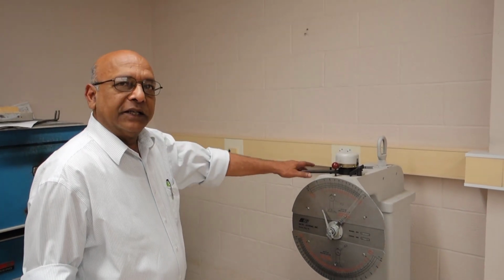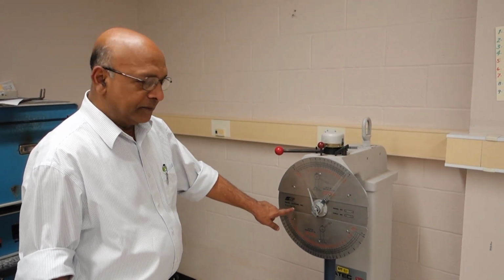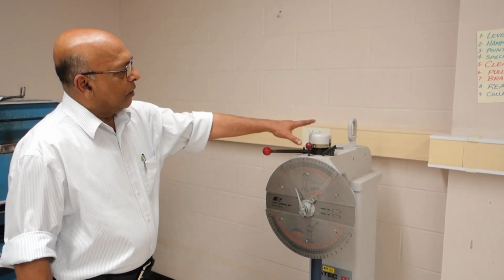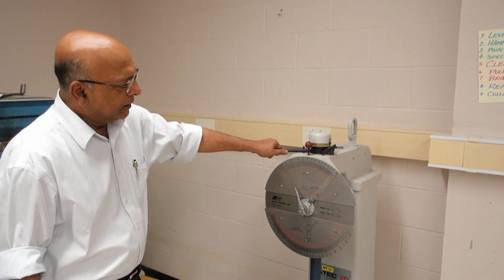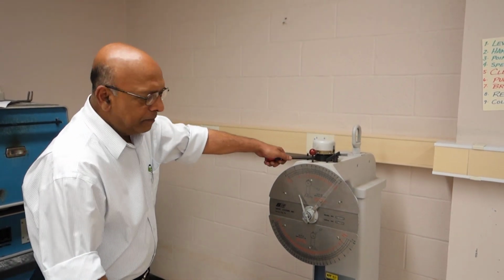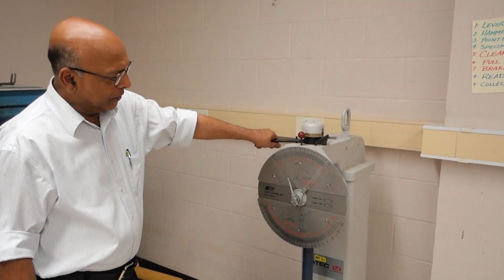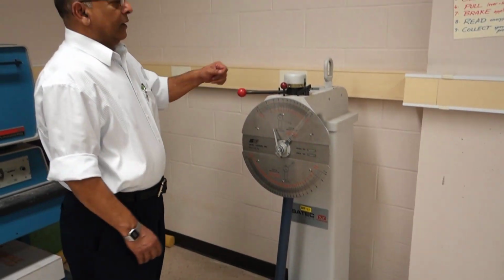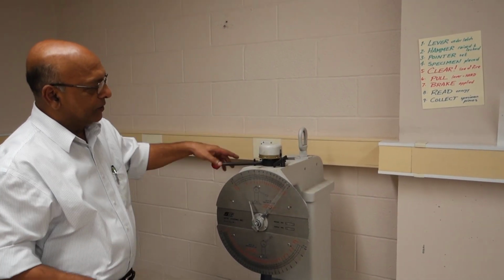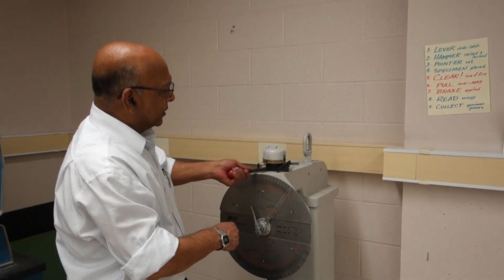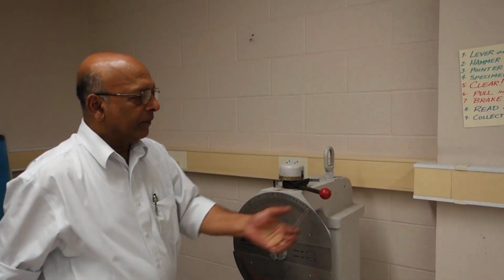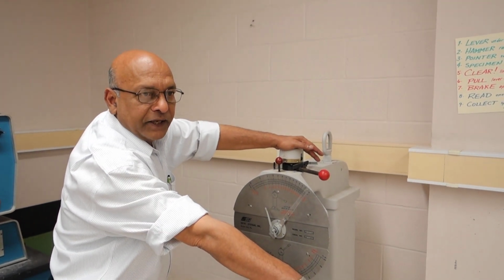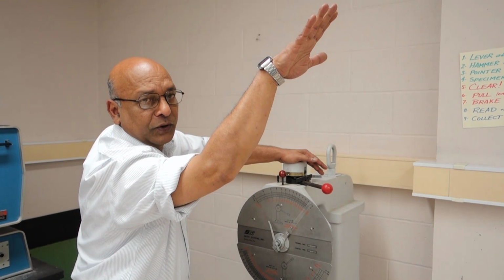Good afternoon, folks. This is our impact tester. It is made by Satec Systems. It is model SI1C3. There are different parts to this equipment. One, we have this lever arrangement which controls the swinging of the arm. Second part is our dial, where we are going to make our readings of the impact toughness. And third part is this swinging arm. So let's start with the top. This lever has three positions: a brake position, a release position, and a latched position. When we put it in latched position, we can raise the arm at two angles. One is at 45 degrees and one is at 135 degrees to the vertical.